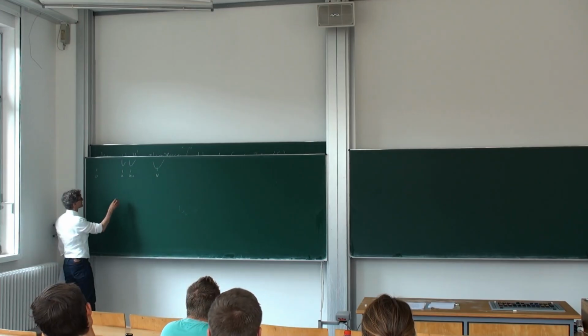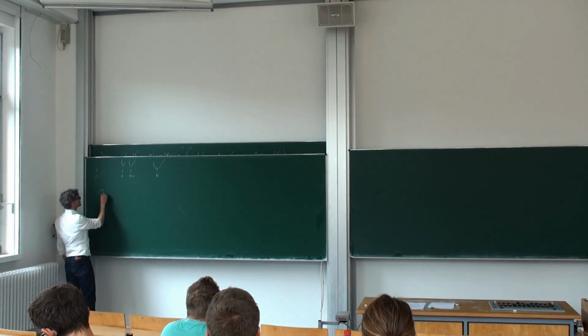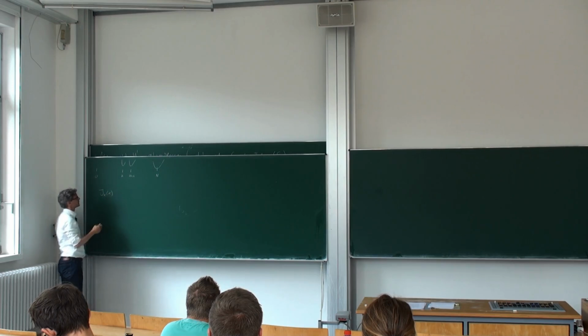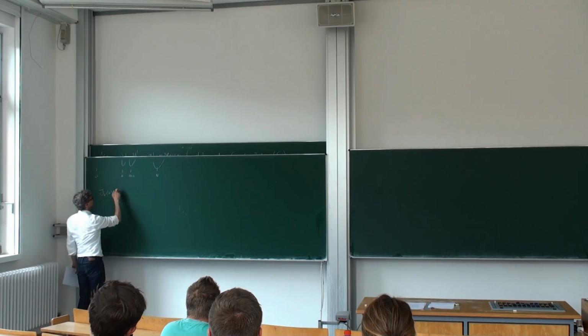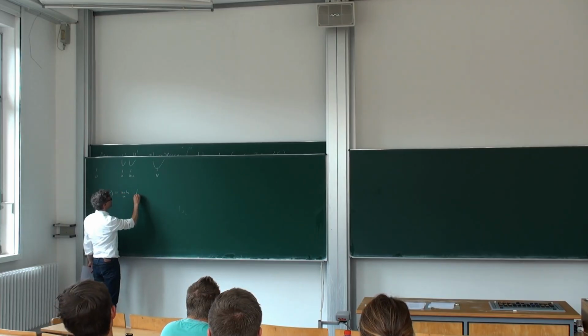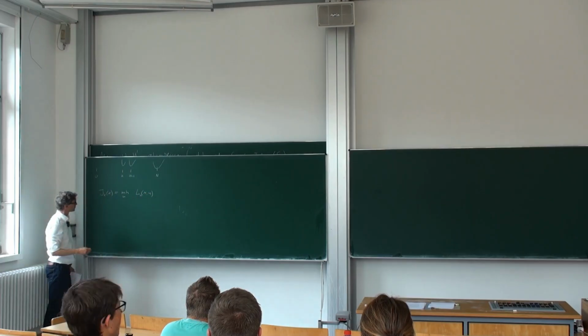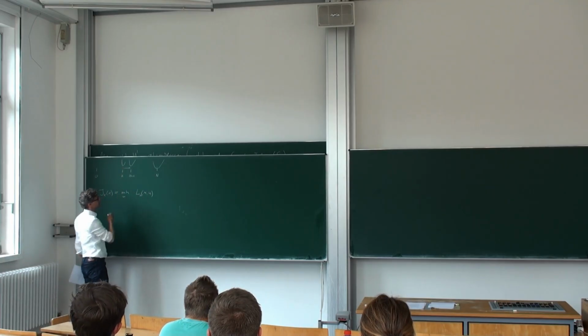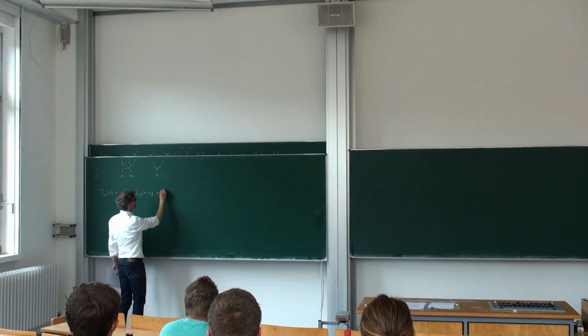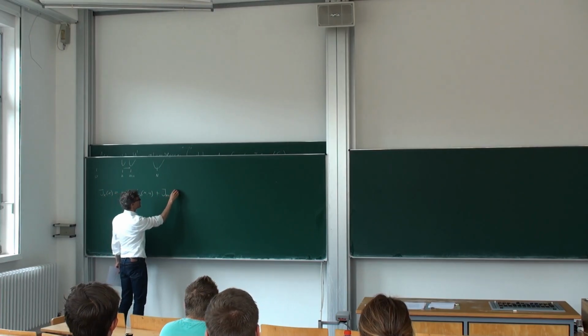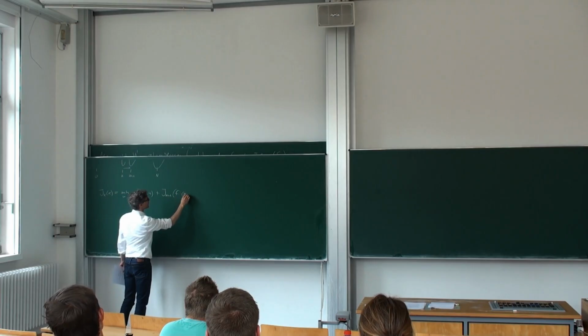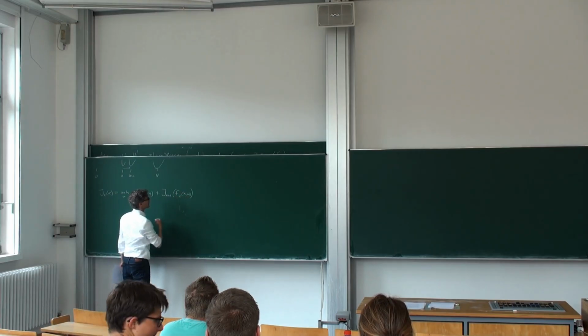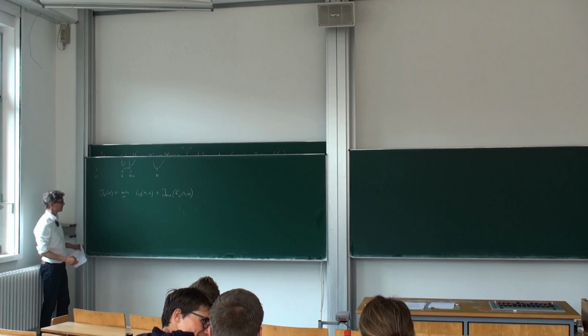And these cost-to-go functions obey a recursion, given by this formula, where the cost-to-go function at that time point is the minimum over all actions u of the stage cost on this transition from k to k plus 1, which could have an index in principle, plus the cost to go that you would end up with after this time step if you let the system develop according to its system dynamics, which of course could also be time varying.